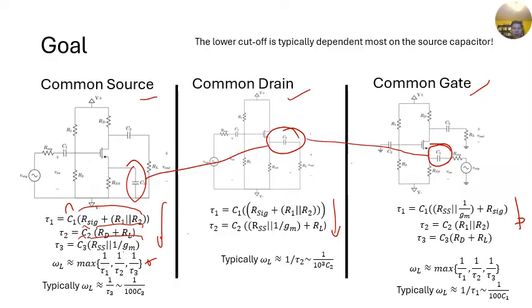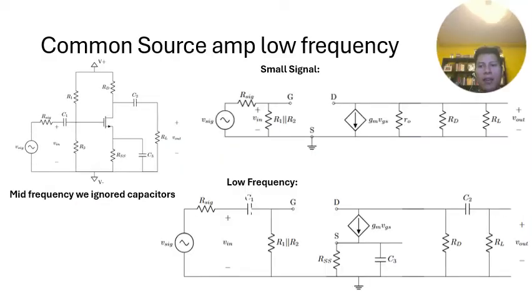Okay, so again, just to reiterate, we have our small signal model, and then we're going to assume that one capacitor fails, and find the R Thevenin, so we treat the other two as short. Once we find our R Thevenin, we're going to move on to the next capacitor and the next capacitor until we're done. So we're going to start with C1.